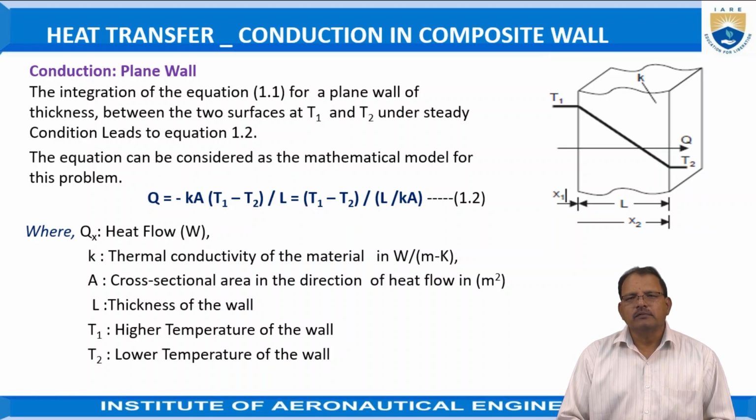The heat energy flows from the inner surface of one wall to the outer surface of the other wall, in which the wall has 2 to 3 layers or 4 layers depending upon the thickness as well as the type of the walls or slab we selected. In that case, the total energy flowing through each layer we have to determine. In most cases it is a steady state condition only. That is, the amount of heat energy flowing through the walls remains constant, but the temperature gradually decreases as it reaches the outside of the outer wall.